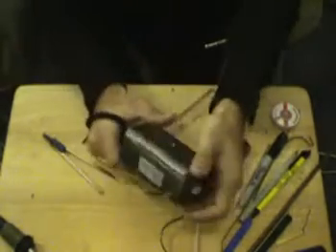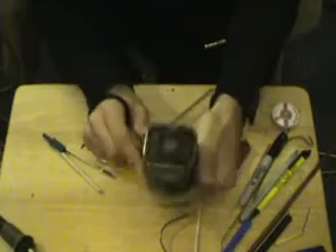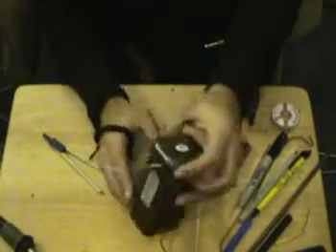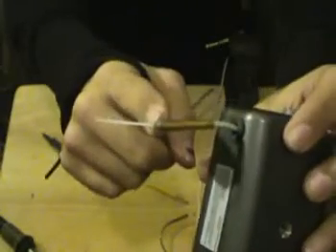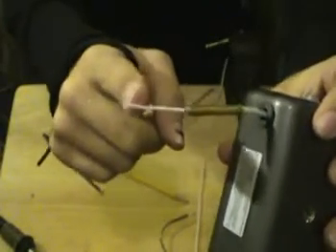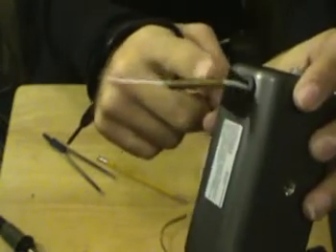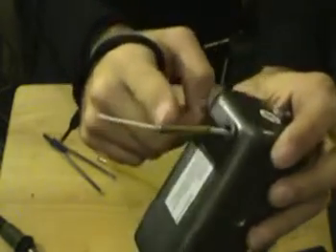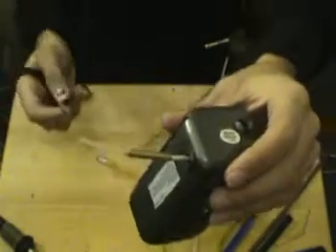And the third product that I decided to go and pillage and destroy for you guys is my 2.4 gigahertz security camera. If you've noticed, this antenna is nothing more than, quite literally, the shield stripped away from the signal conductor, and then a tube has been soldered onto the shield end, cut to an exact wavelength, or I should say size.